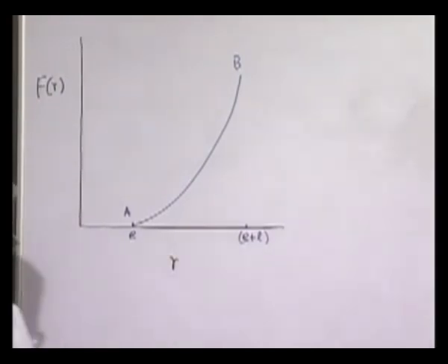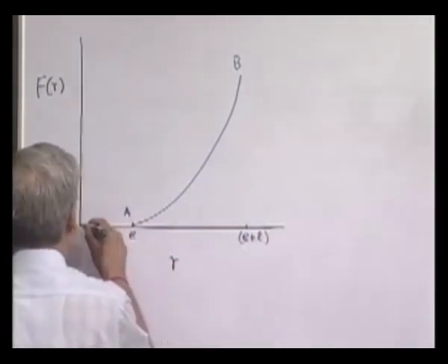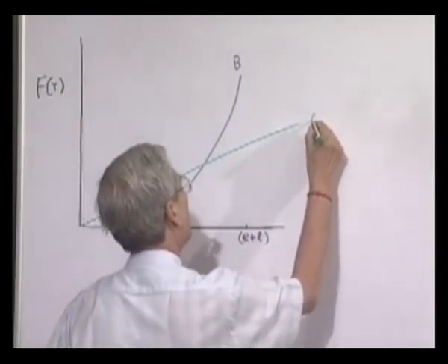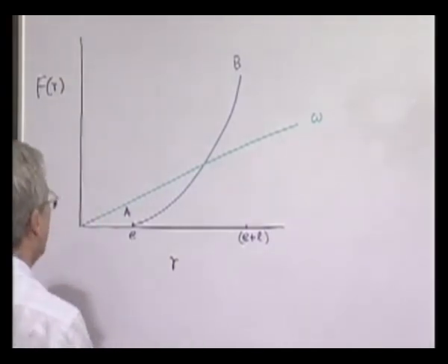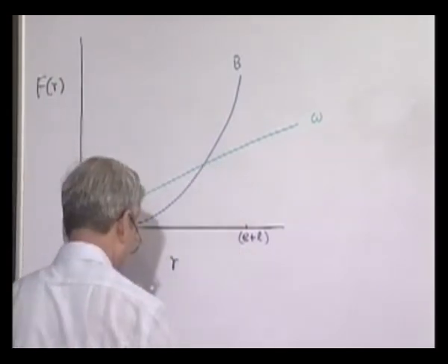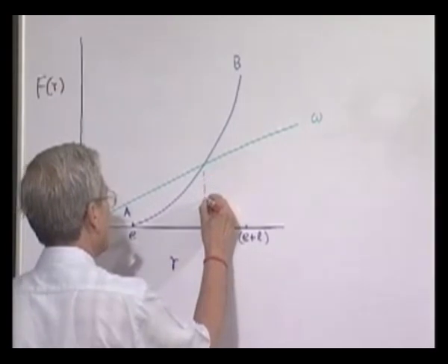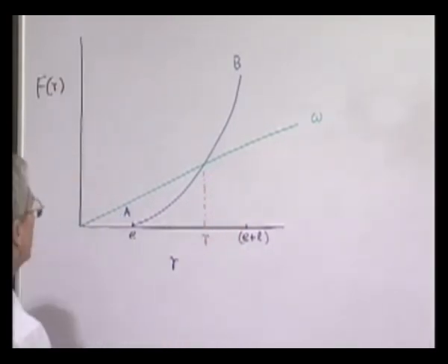So therefore, we find that if we now plot the centrifugal force, which will be just a line for a particular omega, and the slope of this line will depend on the omega, because the slope is nothing but m omega square, and this will be the equilibrium position. If the governor rotates at this speed, then the radius at which the balls will be is this intersection.